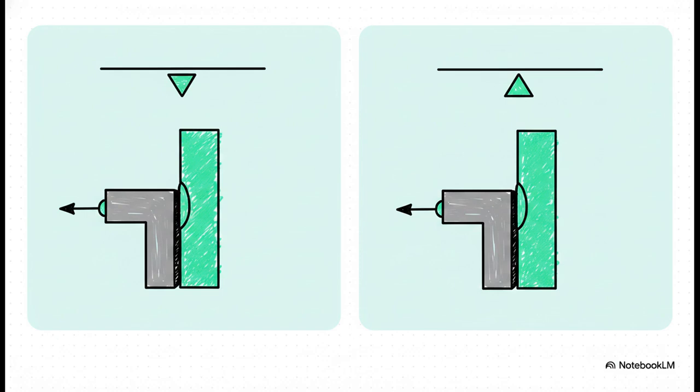Okay, now this right here is probably the most important rule of all. It's the arrow side versus the other side. If the instructions for the welds are below that reference line, you make the weld on the side of the joint the arrow is pointing to. Simple enough. But if the info is above the line, you weld the opposite side of the joint. Getting this right is everything.